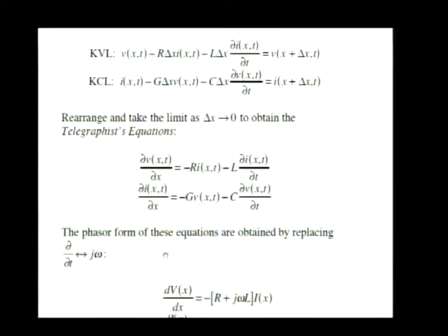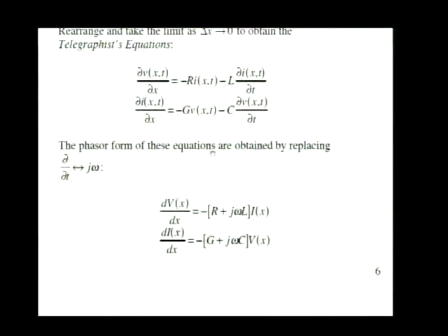All right. Right now, these are very general equations for any time-varying voltages and currents. But now let's do what we were talking about. Let's simplify life for ourselves and use phasors. Let's assume that we're talking about sinusoidal variation for voltages and currents. The biggest simplification that happens when you make use of phasors is that differentiation with respect to time becomes nothing more than multiplication by a factor of j omega. And I write that in my symbolic notation as d/dt's become j omegas.